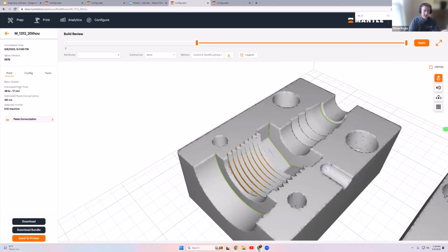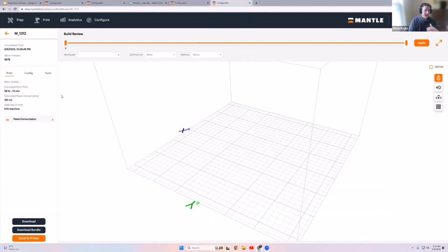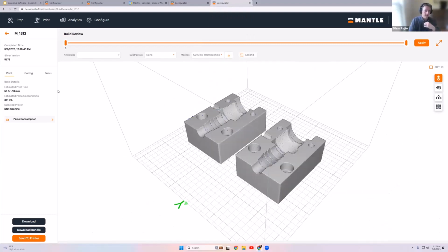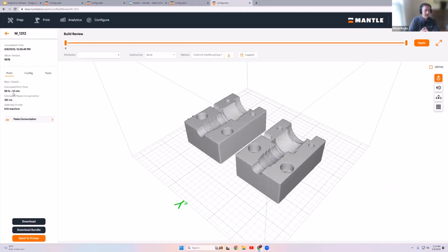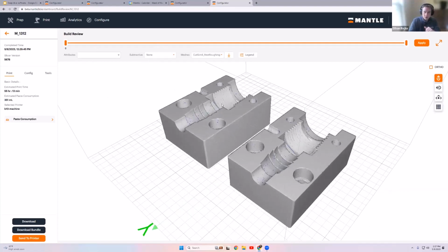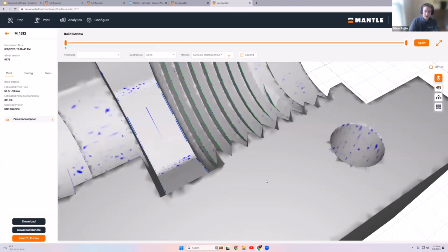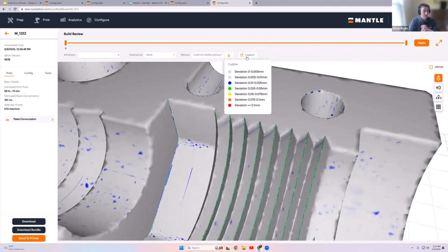You can see that this is a 48-hour print time for both these inserts. Maybe that's okay. We're going to do an EDM burn anyways because we need these threads to be really sharp. If it's not okay, I could go back and do another subtractive strategy. For example, here I did a 6 thou ball end mill. You can see my print time does go from 48 hours up to 55 hours. So I've added 7 hours to the print process because I'm using a smaller end mill now, but you can see all these details in here are much closer in deviation. Let me just get in here and stop moving the camera, because now I'm using a small end mill that's much closer to the sharpness that we need in this instance.